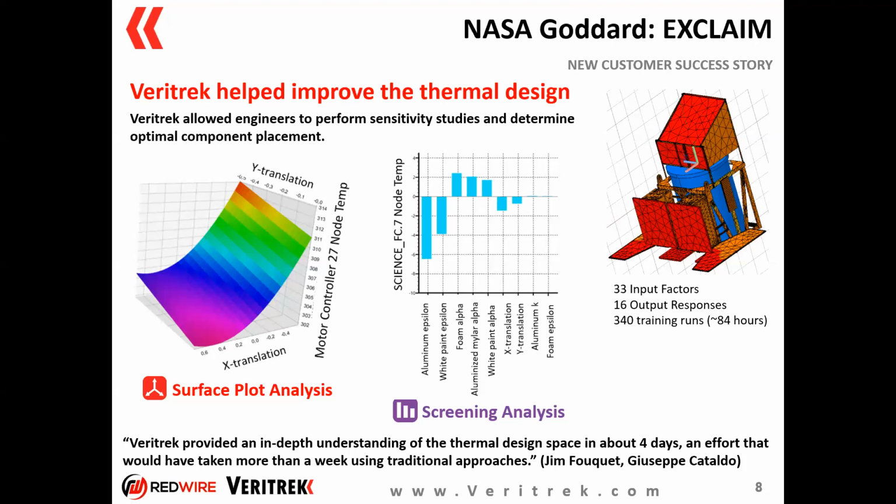The larger the bar graph, the more of an impact, on average, changing that particular input's value is going to have on our output response. And so you can really use this to identify those thermal design drivers and focus your design and optimization efforts on those parameters that do have the biggest impact on your output response of interest.